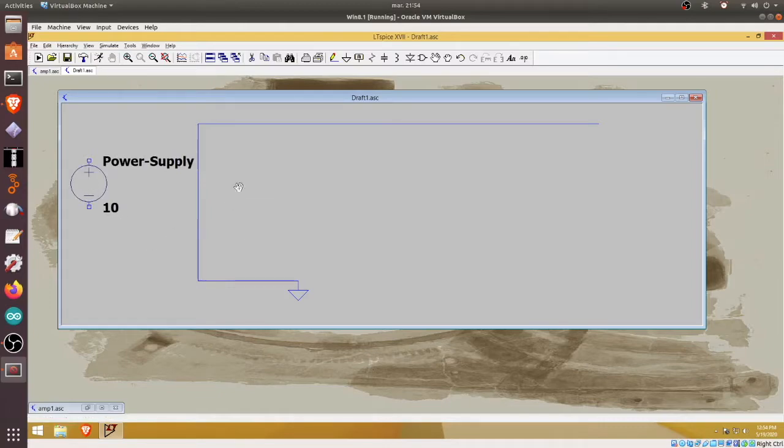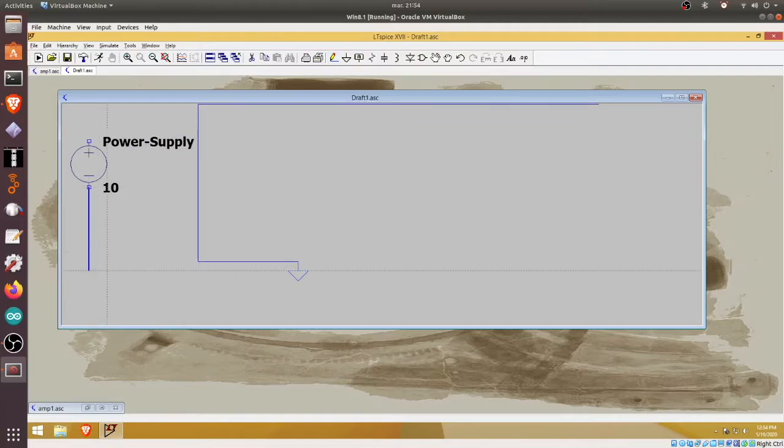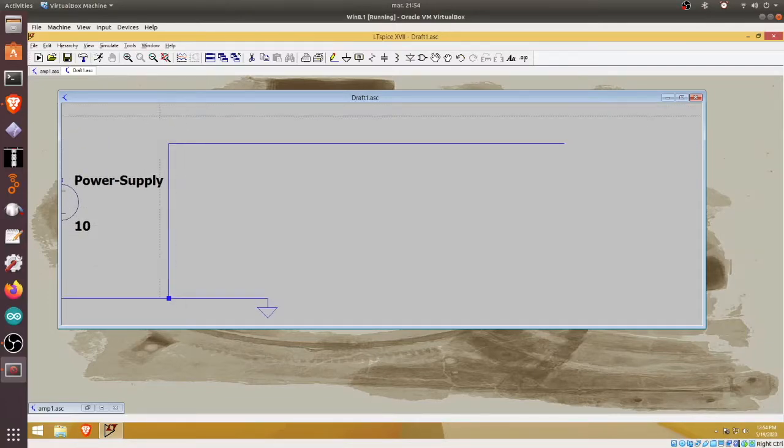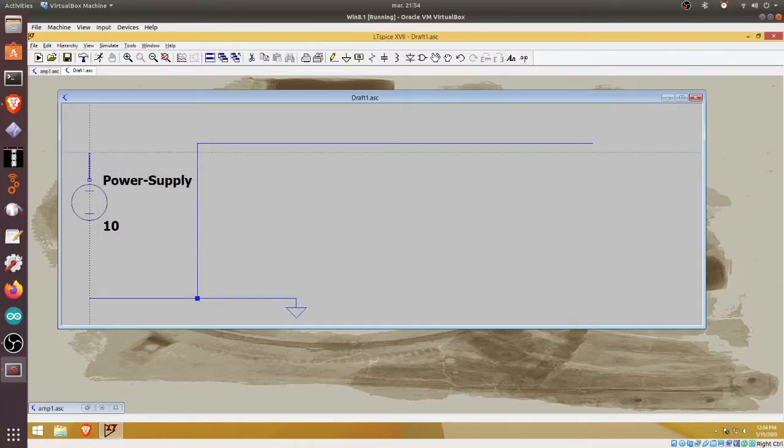Okay, like here, perfect. I'm going to connect the power supply minus sign, the negative terminal, to ground, like that. And okay, good. And perhaps let me also connect the plus side to this other line. Okay, so this is going to represent our positive rail. Of course, now we have sort of shorted the positive rail to the ground rail by doing that, so let me just eliminate this wire, it's not needed anymore. Okay, perfect. So this was my DC power supply.